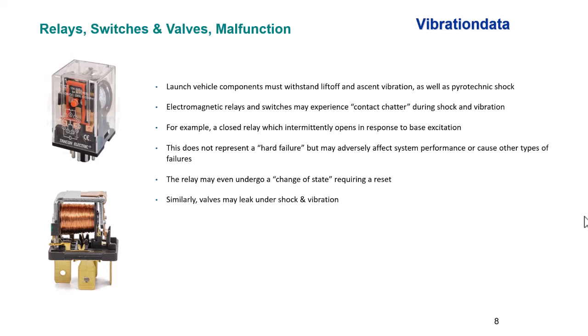So let's take a relay that is normally closed. Under shock or vibration, the contacts may open up, and that's called chatter. Well, is it okay if a normally closed relay all of a sudden is open for a millisecond or so?